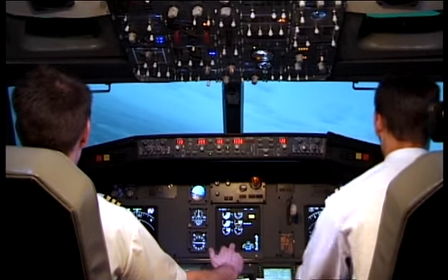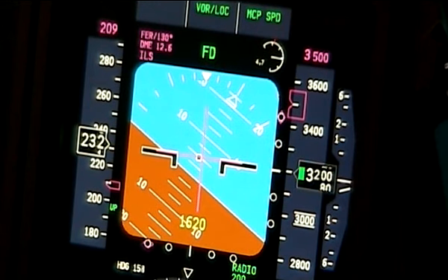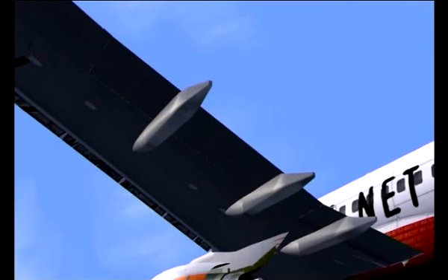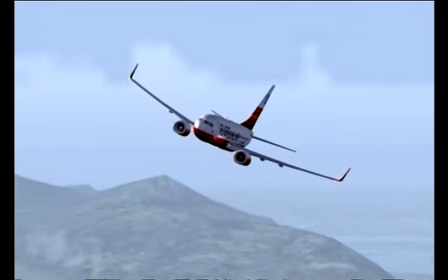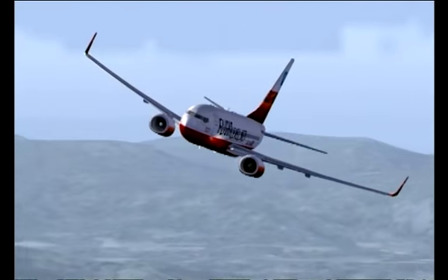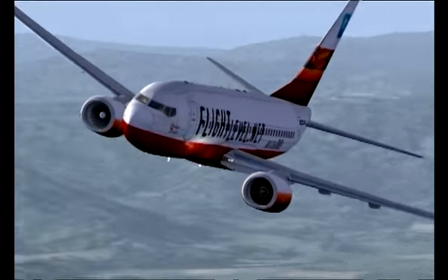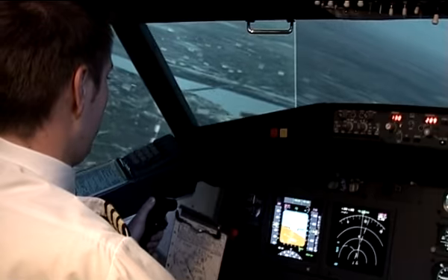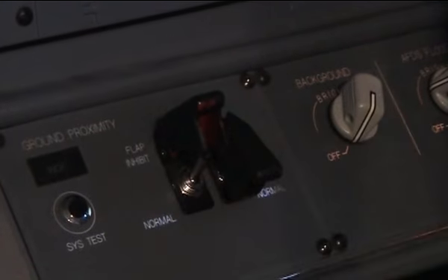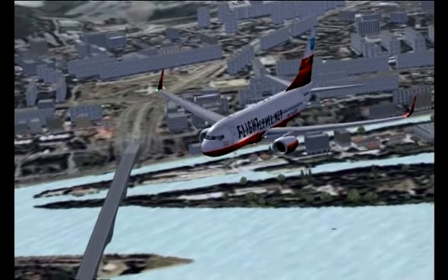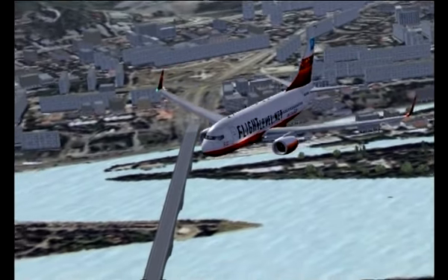Too low flaps. Too low flaps. At lower altitudes, the aircraft's automatic systems warn of flaps position. But now, this warning should be ignored and muted with a special switch. Flaps inhibit, please. Too low flaps. Some more checklists, and the approach briefing.